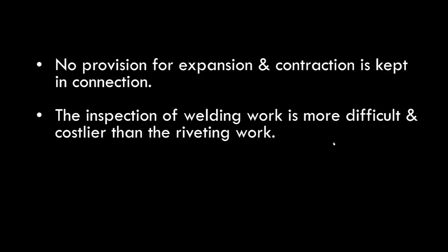The inspection of welding work is more difficult and costlier than riveting work. As I said, welding requires skilled labor, and that's why it is costlier, and the inspection is a little more cumbersome. In this case, you require non-destructive testing. If you want to inspect the welds, you have to perform some NDT tests. This is why it is costlier than riveting as well as bolting. You can see a defect in a bolt or a rivet just by looking with your eyes. But in welding, you require some kind of sensor to judge what defects you have inside the weld.